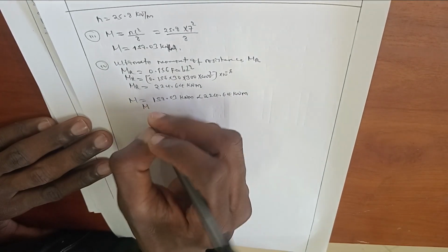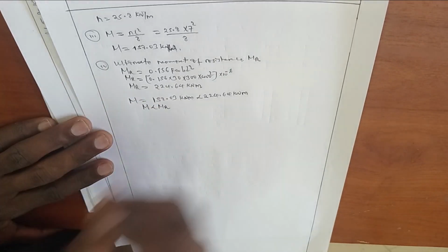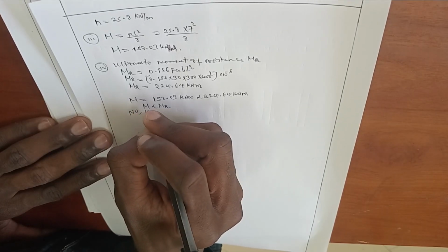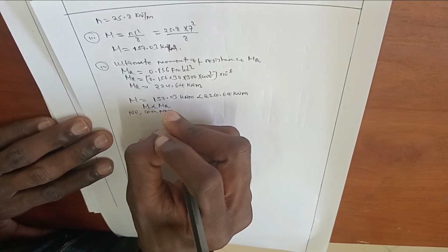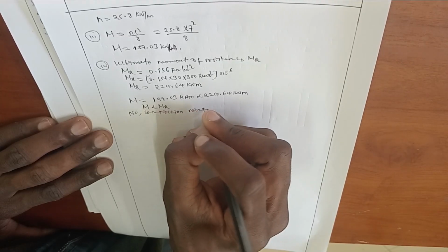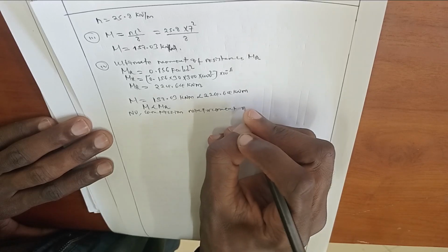Since the maximum design moment is less than the ultimate moment of resistance, hence no compression reinforcement is required.